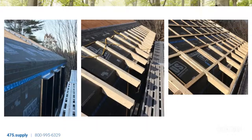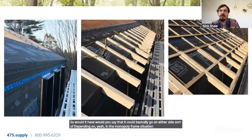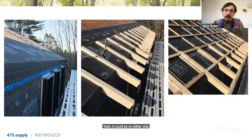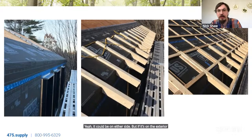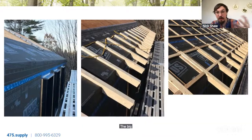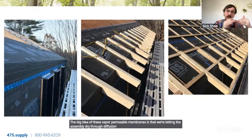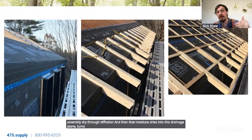So would you say that it could basically go on either side, depending on the situation? Yeah, it could be on either side, but if it's on the exterior, I would want to ensure that it's vapor permeable. The big idea of these vapor permeable membranes is that we're letting the assembly dry through diffusion, and then that moisture dries into this drainage plane, turns to condensation, and sheds away.